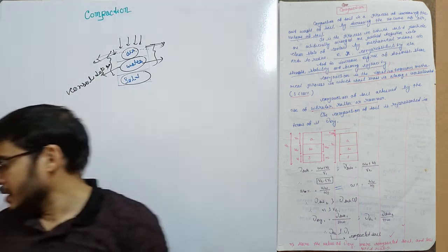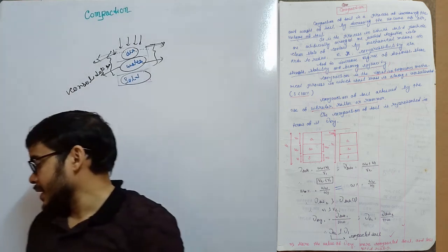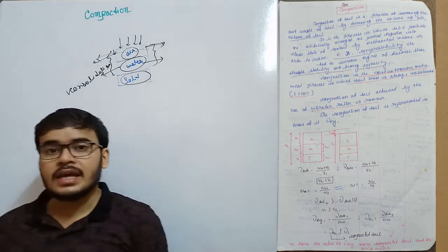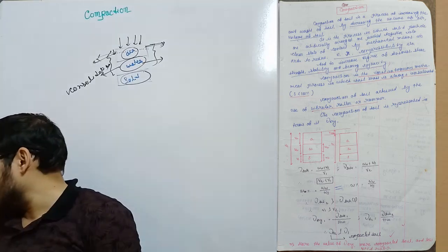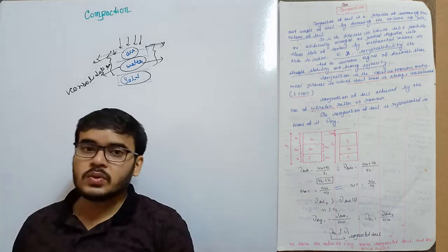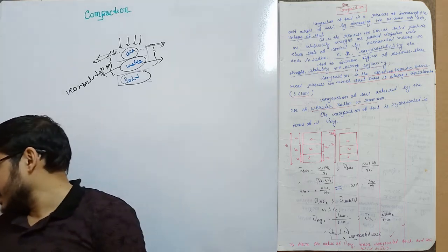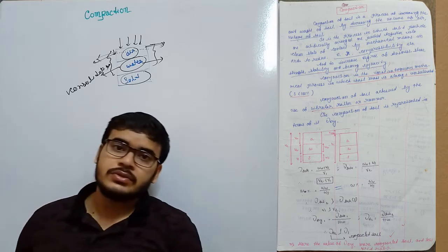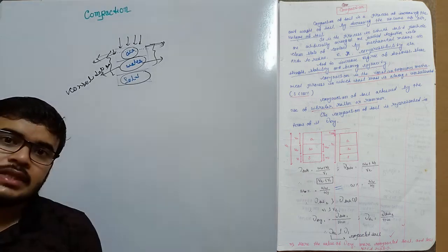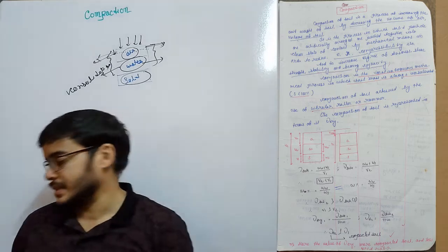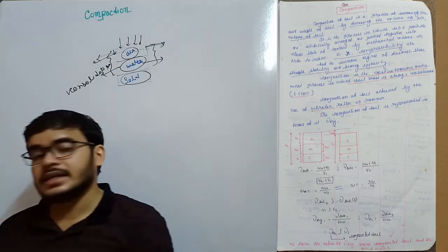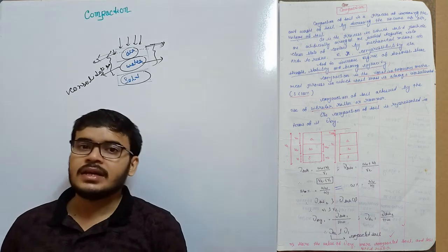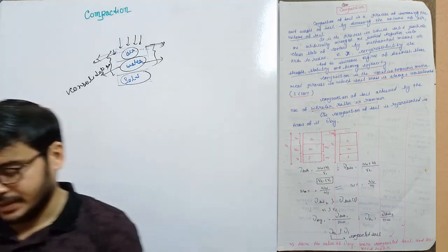The next line is, it is the process in which solid particles are artificially arranged, packed together into a closer state of contact by mechanical means, in order to reduce void ratio, porosity, compressibility, etc., and to increase the degree of denseness, shear strength, stability and bearing capacity.